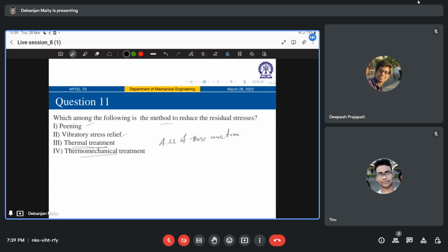So what is the summary then? Whatever we have learned from today's session, or from your video lectures. In summary, we can say that the severity of heating and cooling associated with the thermal cycles, which is of course typical for fusion welding processes, always results in thermally induced strain and stress, right? And because of this thermal strain and stress, it can lead to severe distortion. So these things are integrated: residual stress and distortion, right?